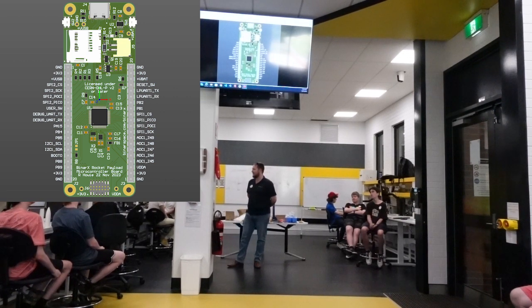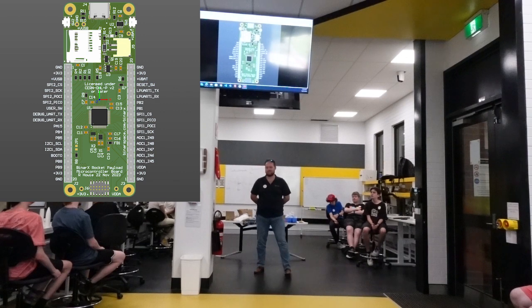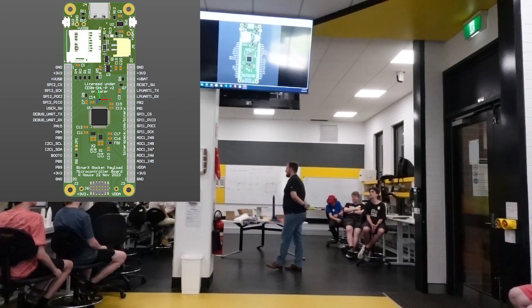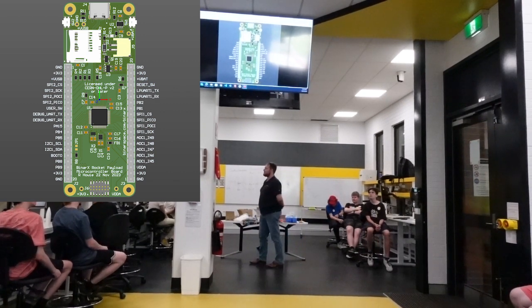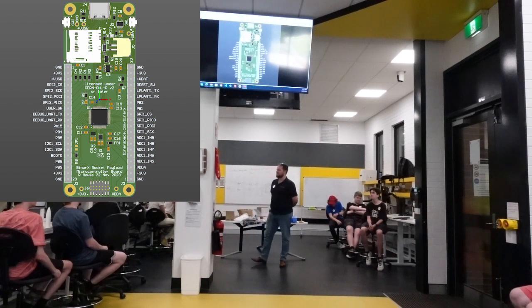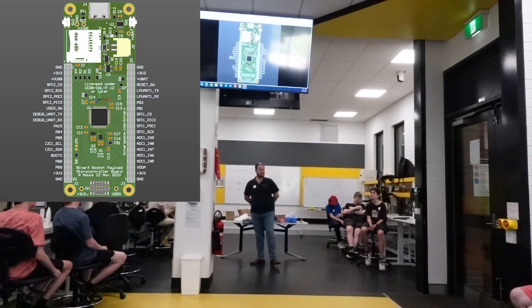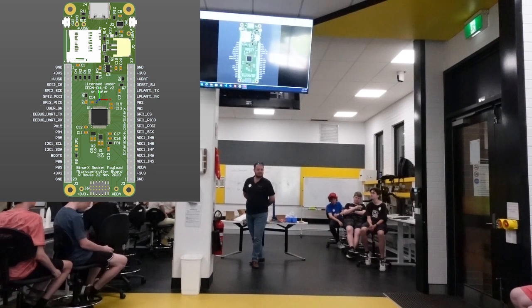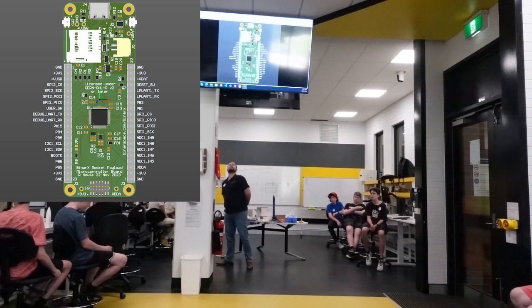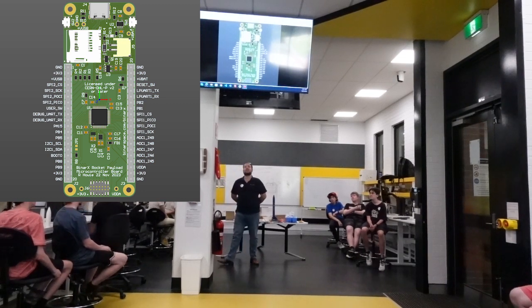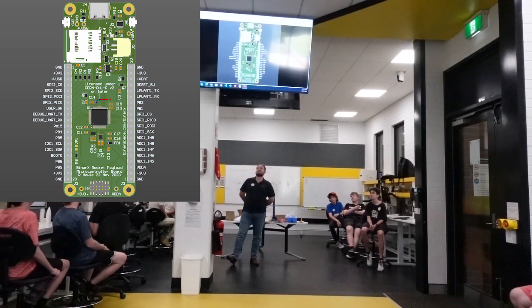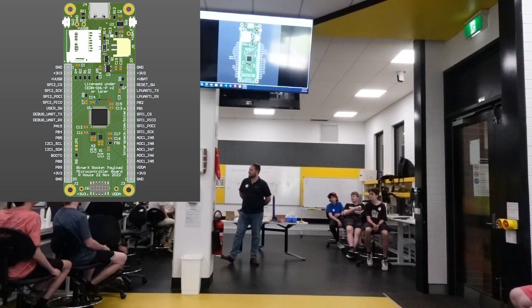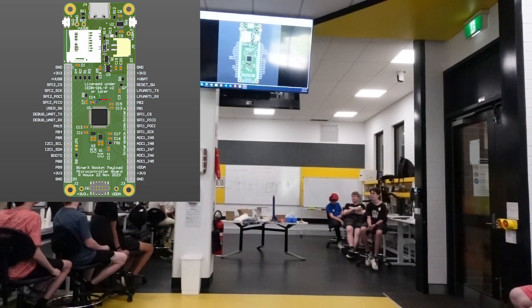So what we're going to be going through today is an extension from what Fergus was talking to you about this morning. Just going through electronic circuits and actually building them physically on a breadboard, testing them, and then checking that everything works correctly, and perhaps getting some stuff working with your dev boards. So, what have we got up? We've got the picture of the breadboard up here. First thing we're going to go through is getting your power rails set up on the breadboard itself.